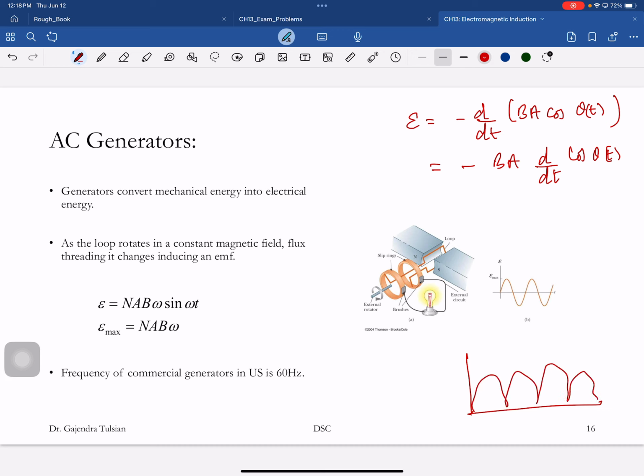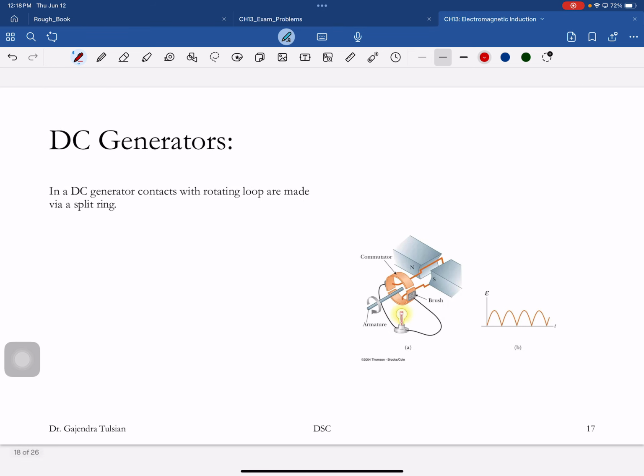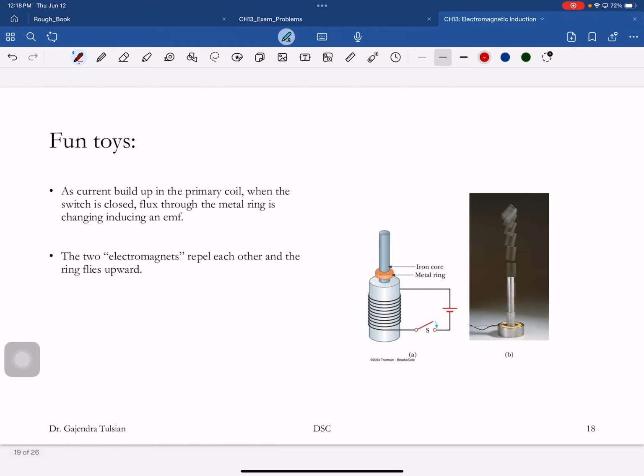So the bulb is going on and off 120 times a second. How come you don't see the flickering? It's too fast for our eyes to see. Anything faster than 30 times a second, you can't. So if the wire is connected to the outside brushes like that, that's the voltage you get, yeah?